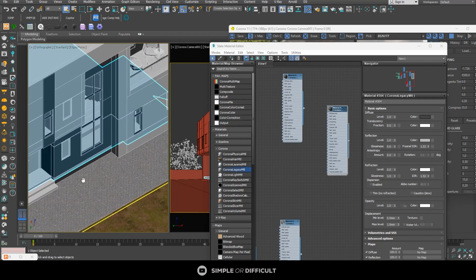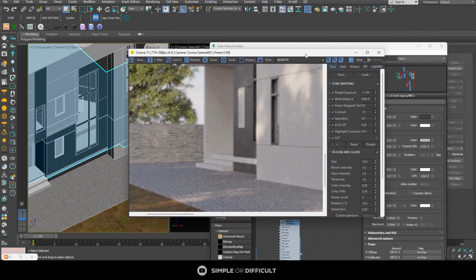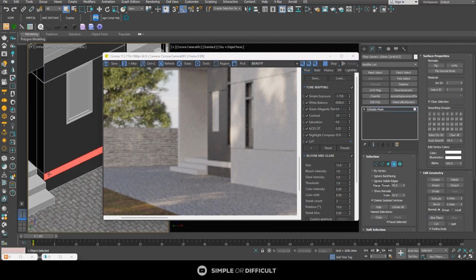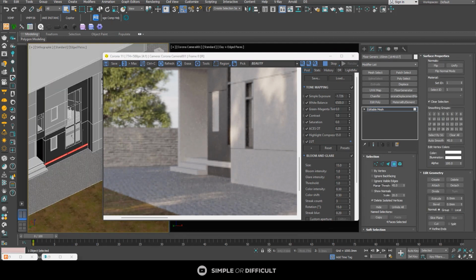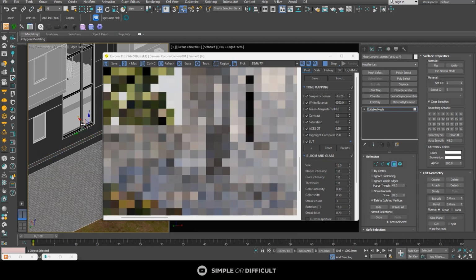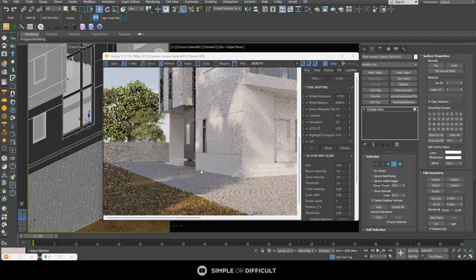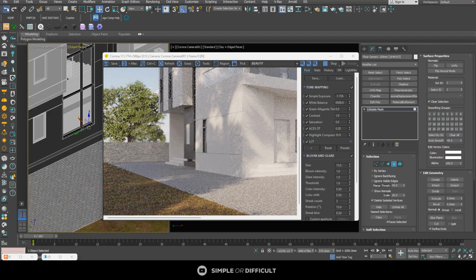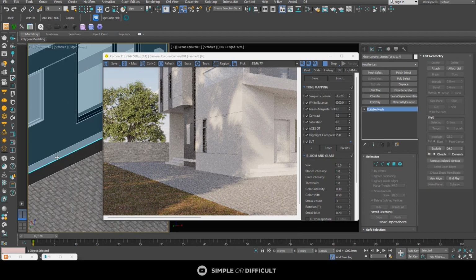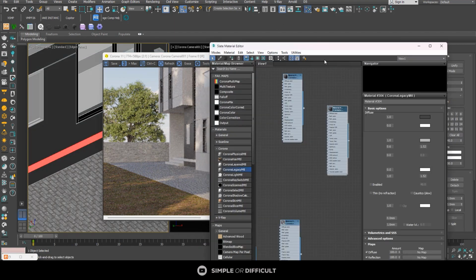Oh, wow. So I'm just going to move it in. All right, so to move it in, all I have to do is select this one over here, select the face, use the move tool, and just move it in. Now when I do that, you find out that we're having space here. So I think I will just bring it back out. Okay, and then select this face here. Let me just use this too, and then apply the same material to that face.